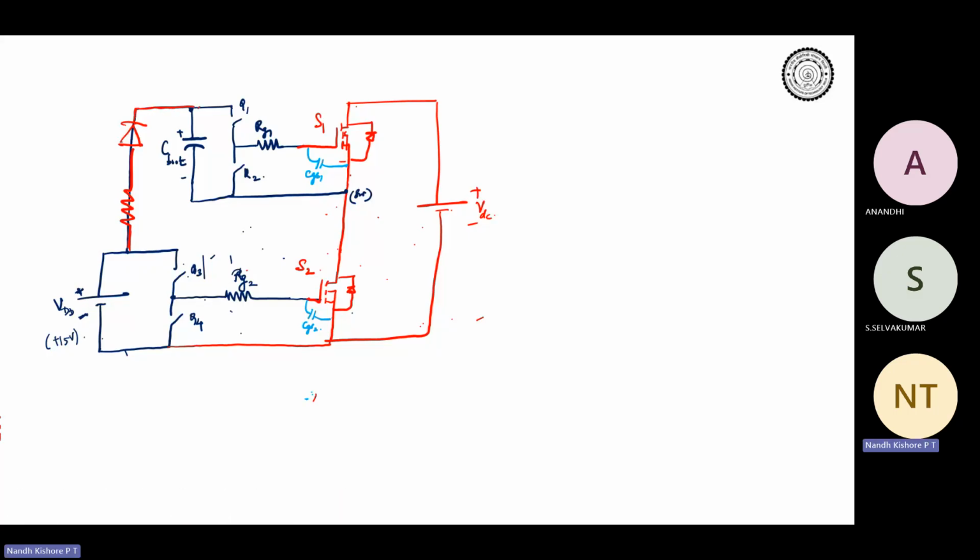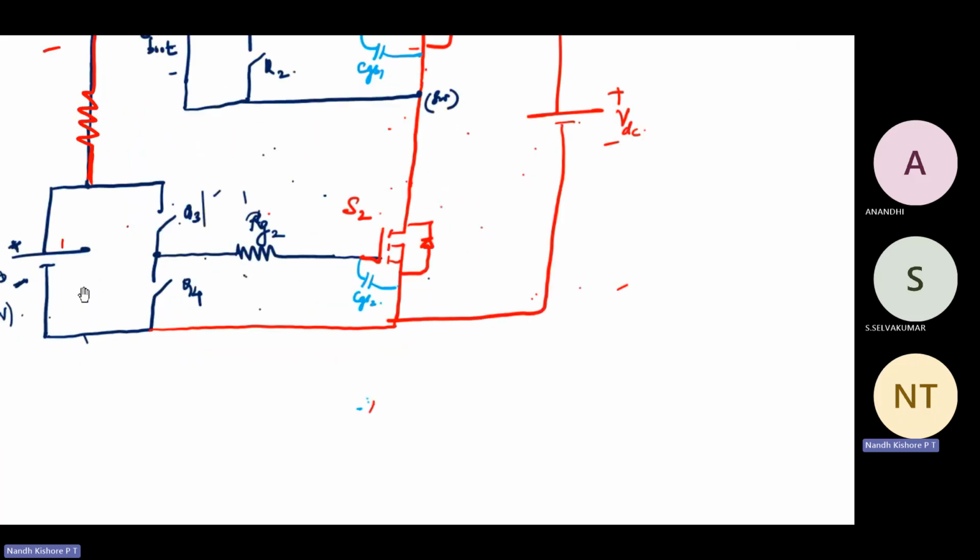When the diode is off, we have to find out what is the voltage across this diode, VD. That will give us how to size up the diode. So we will just write a KVL equation for that. Let's start from VDD.